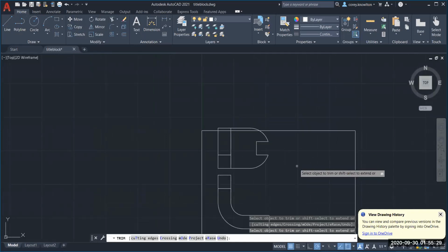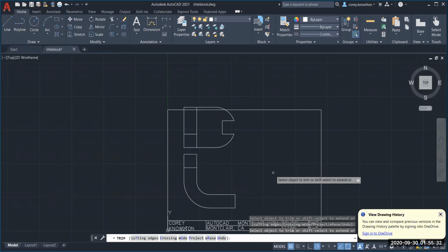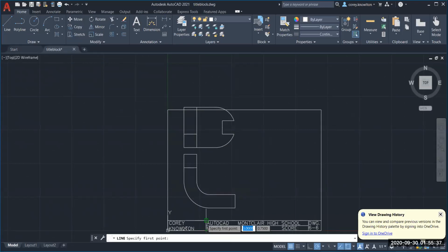And the last thing I'm going to put in is the right side view. Let me start by going a 1/2 inch over from here. I'm going to go 0.5 over. And then it's 3 inches wide by 4 inches tall. I can get a line coming straight over from here. There's a little notch out of this, and that is from here over.